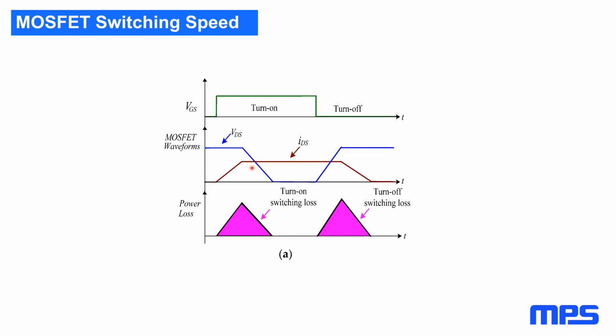Okay. Next, how do we measure inductance in the gate loop? Boy, that would be hard to measure because the gate loop includes basically everything from the gate driver IC's supply through the gate driver IC to the gate, then across through the capacitance to the source.